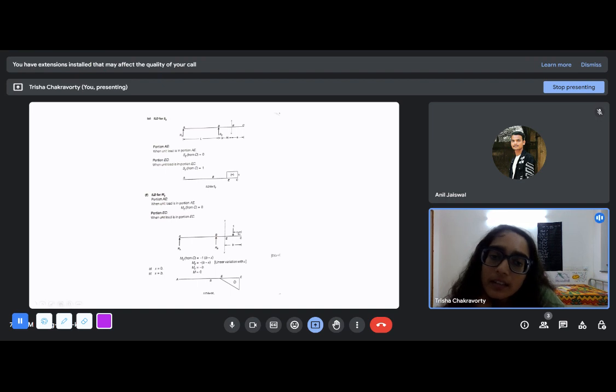This is another section that we are considering. Like if suppose we want the shear force or bending moment ILD at this section, so they will change. So here again we have to consider three portions, AB, BE, and EC. You will see that whether it is in AB or BE, if you come from the right side, you will see that there is no load encountered. So no shear force encountered, no moment encountered. So the ILD for shear force or bending moment will be zero up to this point E.